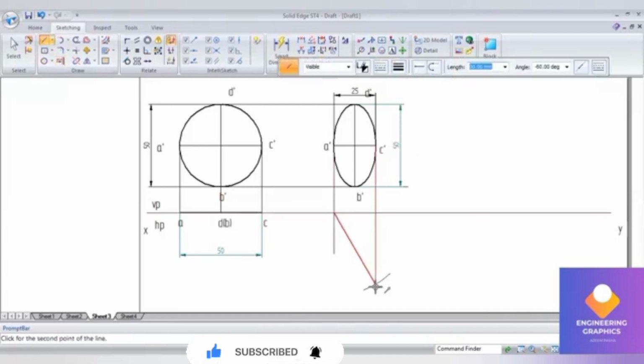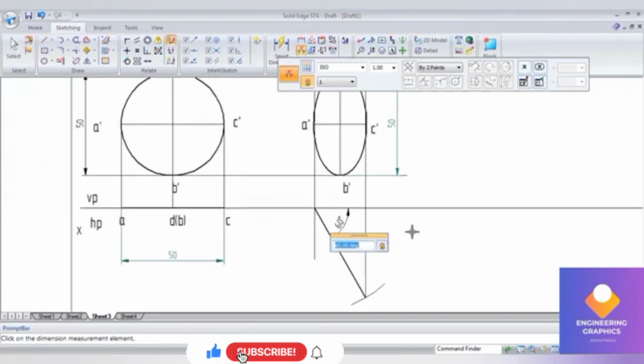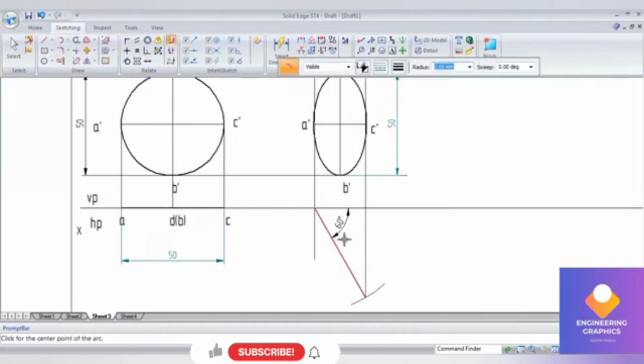to find out the angle, because we don't know how much angle it has been inclined, so that in the second position it is converted into ellipse. So we are finding out angle. So the angle we are getting here is 60 degree. Now second arc also I'll cut. So it is exactly at 25 mm.